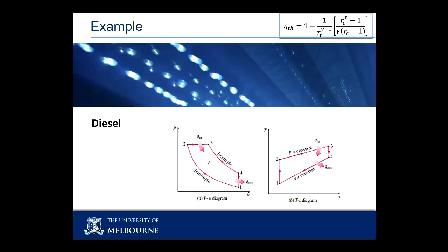So, what we're going to do now is the counterpoint. Reciprocating engines, closed volumes, Cv delta T, Cv delta T, Cv delta T, except for the heat addition in a diesel process. That's the catch. The thing we learned as we were studying diesel process is that because the heat addition in a diesel process has a change in volume, we solve that one with enthalpy, not with internal energy, which means we solve it with Cp delta T, not Cv delta T. We'll do that in the worked example. I just want to refresh that idea.